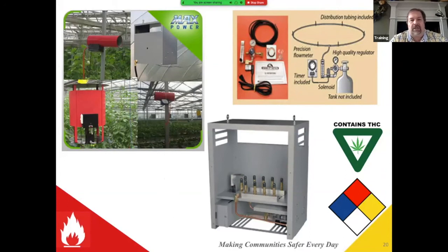So in areas that have conceded to normal outdoor fresh air rates, you know, they may be okay with that. But here's the problem. That says the unit comes brand new, installed out of the box. And I really want to stress that, because if you've ever looked at an unvented heater after it's run for even a week, they start to collect dust because they circulate air through there just by the convection process. That little bit of dust starts to turn that flame yellow. And now your ratio of carbon monoxide, carbon dioxide, and NOx produced are hugely altered from its originally installed condition. So these things require constant maintenance, constant checking.